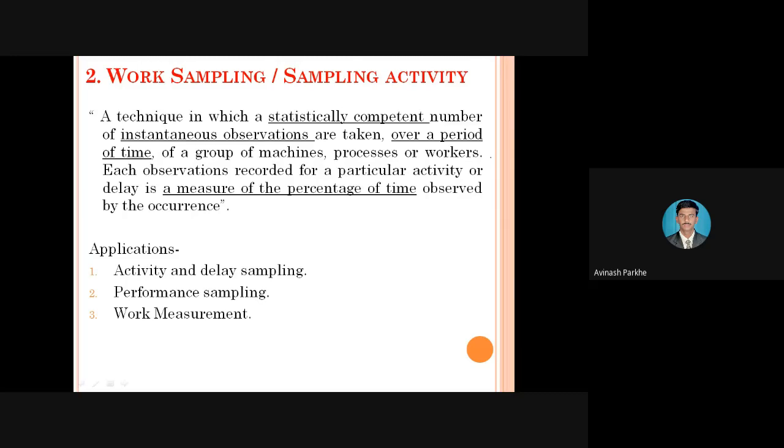So whenever we are performing the task, if you have to go for drinking water, if breakage of the tool is taking place, if you have to change the tool, or change the coolant oil, some unavoidable activities are also there. So at that time, the different types of allowances are also provided. If I have to measure the total standard time, then standard time is equal to basic time or the normal time plus allowances. Like that, a simple formula is there to calculate the standard time.